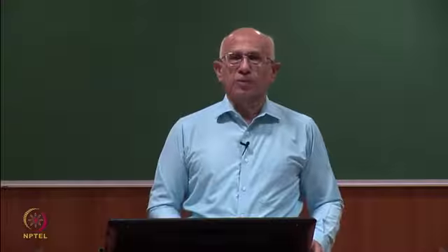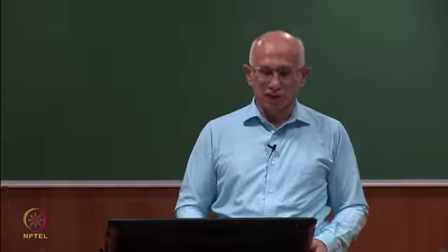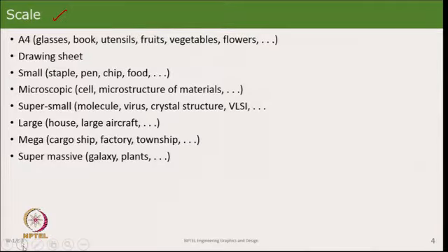So, let us begin with some aspect of a drawing, which is what is called the scale or the scaling. So, what do we mean by scale? It is that we see objects and we see in relation to some other size. In making drawing sketches and in engineering, our standard is a drawing sheet, which as a standard sheet that we look at is an A4 sheet. A4 sheet is an Indian international standard, which tells you that the size of the sheet is 210 millimeters by 297 millimeters.